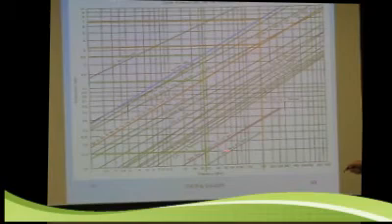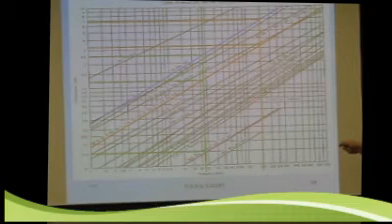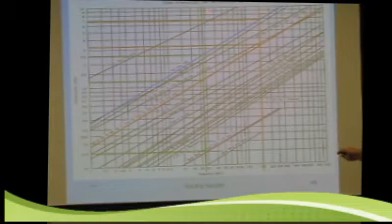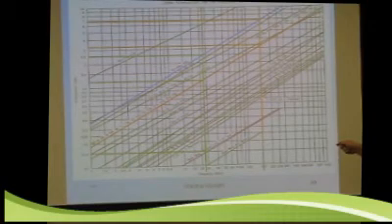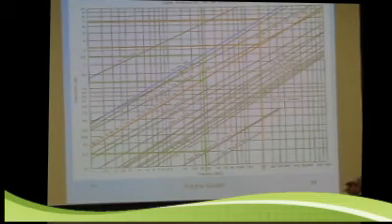Most people don't use open wire. This is 7/8 inch hard line, which is extremely expensive. This is, by the way, usually attenuation per 100 feet. So if you have 100 feet of even hard line, you're going to lose 6.6 dB. That's the best stuff you can buy, more or less. So at 150 megahertz, if you can keep the cable runs short, you're going to help yourself, because you just lose a lot going through coax at that frequency.